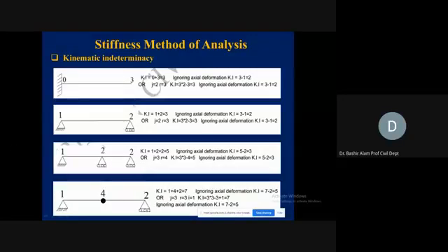So 1, 2, and 2. Now these are the degrees of freedom at each one of these joints. So if we add them up, it is coming 5. So 5 is written here. 1 plus 2 plus 2. Now, if it is given that you ignore the axial effect, 1 member and 2 members we need to subtract. So this is becoming 3 degrees indeterminate.